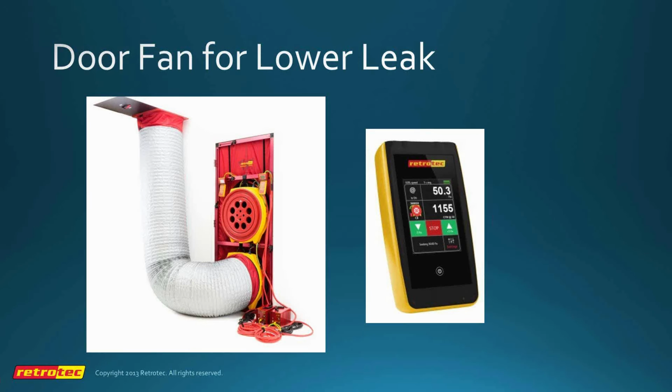So this assumes that this fan here is capable of blowing enough air to pressurize the above ceiling space. Now, obviously, if we look above the suspended ceiling and we can see 5,000 square feet of warehouse and so on, we're never going to pressurize that space. We have to be able to pressurize that space in order to neutralize the pressure across that ceiling so we can isolate the lower leak. So it's okay if that above ceiling space extends into adjacent offices, but we need to be able to pressurize that cap to neutralize the pressure across that suspended ceiling.